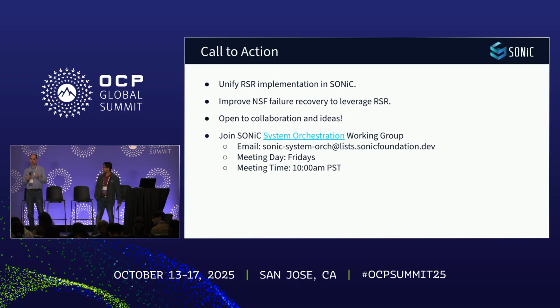After it finishes pushing that new configuration, that resume process is what we call a soft reset of the device. It's a similar technique that can also be used, for example, to recover from a stuck pipeline or things like that, where it's resetting via specific sequences and register writes in the device, telling every block, just start over from scratch. So everything that's been queued up in the buffers is gone. Everything in the traffic management, scheduled credits, everything's reset almost to an original state. So anything that's been queued up will be flushed at that point.